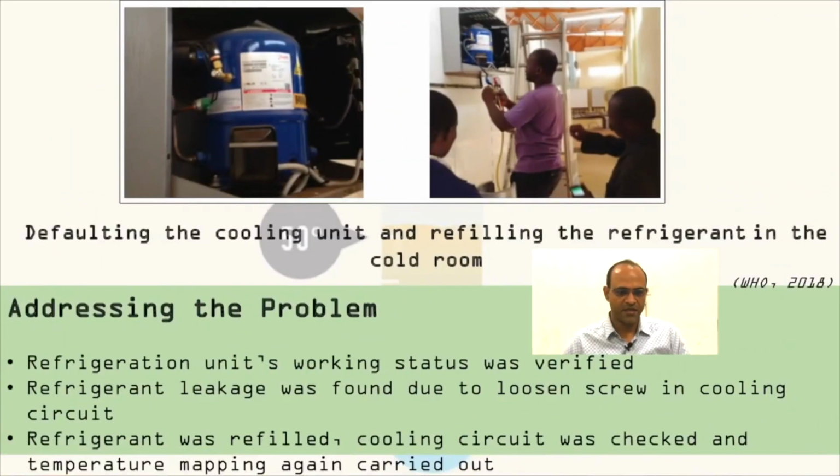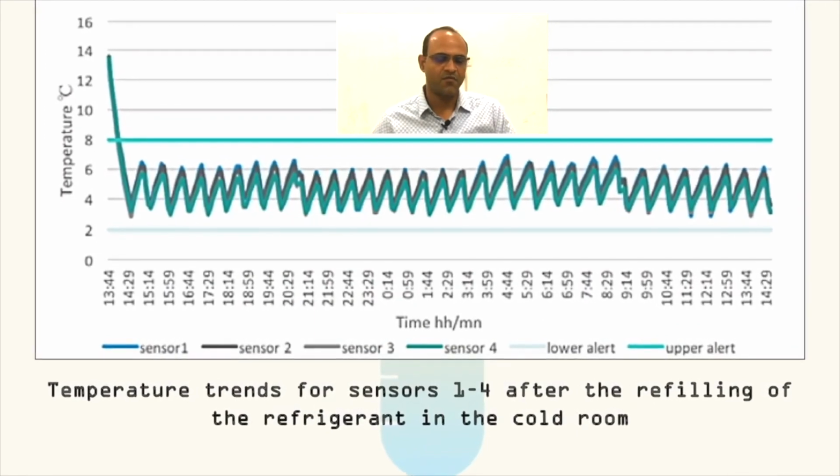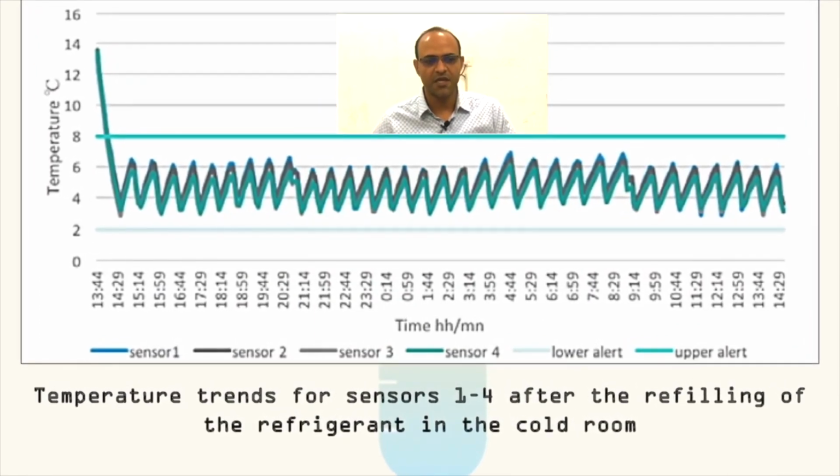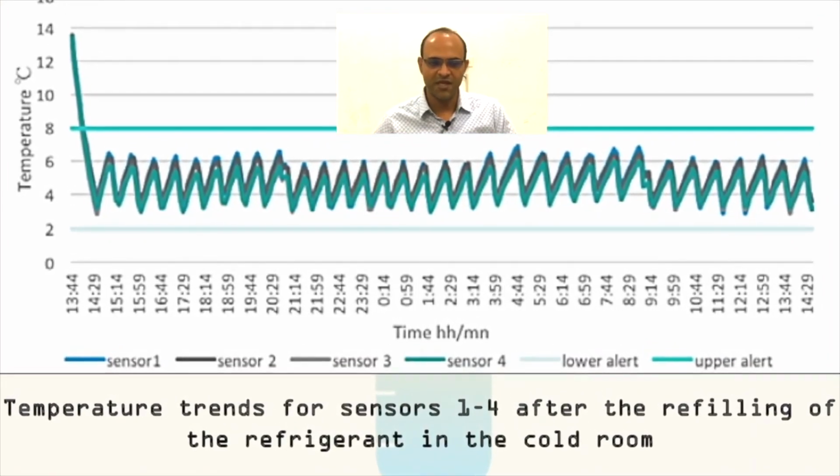Now, addressing the problem, this may be due to a default in the cooling unit and the need for refilling the refrigerant in the cold room. This might be the reason the compressor is not working properly, because of the lower amount of refrigerant. The refrigeration unit working can be verified. Refrigerant leakage can also be checked. If there is refrigerant leakage, the cooling circuit should be properly checked. And then temperature mapping should be carried out again for such cases. Once the rectification has been done, the same is plotted again, and the temperature for these 4 sensors is found within the acceptable limits.